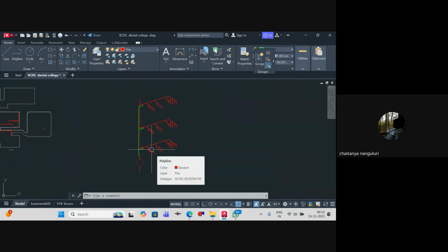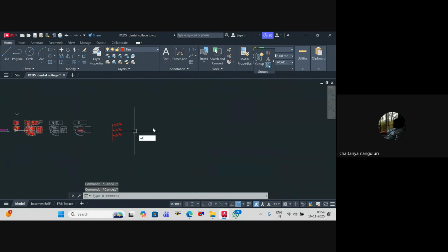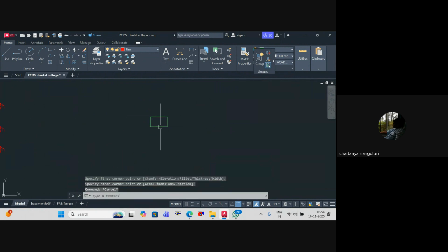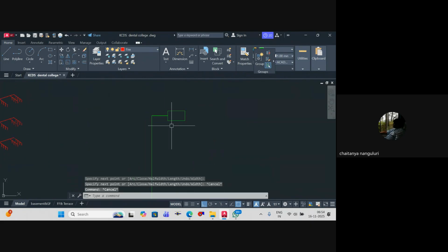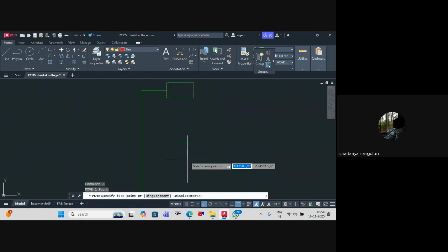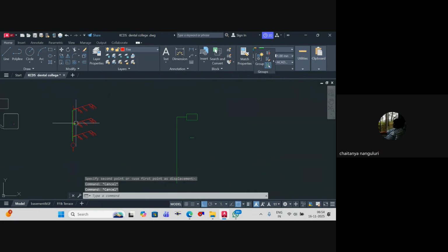Understood? Along with that, generally we have your hydrant drains also. That also, if possible, we'll connect it to this same drain. Let's say you've got a hydrant valve. I'll just explain it here. So this is your hydrant valve. When you have a hydrant valve, there might be some leakage later, or you might have opened it. So for that reason, we generally provide a flow drain. The plumbing consultant will provide it; it's not mandatory or a rule. Generally your hydrant main and your sprinkler main will be running parallel to each other. Understood?